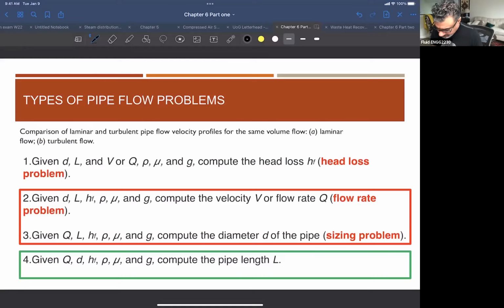So last time we talked about fluid flow in piping systems, and we basically covered the friction losses between 2 points on a pipeline. If you remember, we said, okay, if we have a constant diameter pipe that is carrying fluid from point A to point B, we can apply the Bernoulli equation between these 2 points. We know the condition at point 1, and if we know the condition at point 2, we can calculate the losses between 1 and 2.